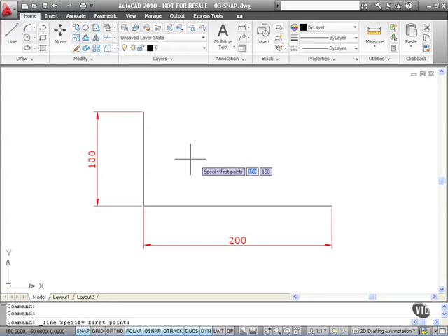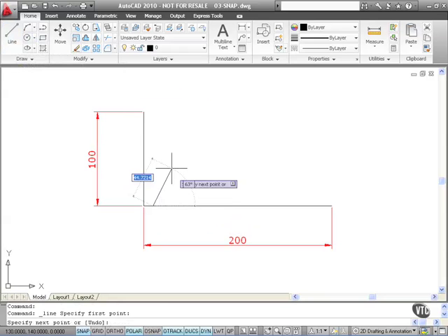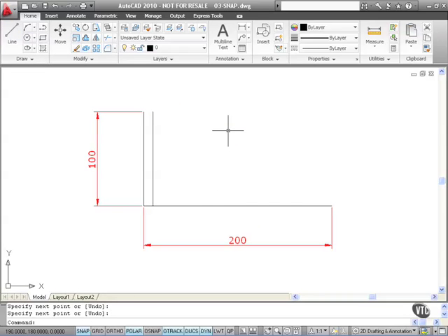So just hit Escape there and go down to the status bar. Click on OSnap once. That'll switch it off. Now Snap is on, but OSnap is off. So now when I draw a line, I will get that increment to work. There you go, look. I come up there, line it in, left click, Enter to finish. I'm drawing exact increments without any object snaps. It's a bit like that phrase, look mum, no hands, isn't it? But the good thing here is I'm using my snap tool with my specific settings to draw my lines.